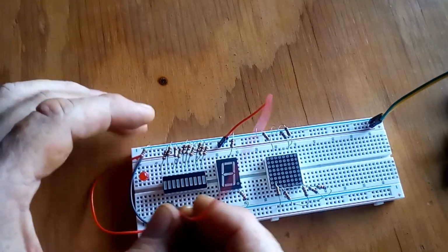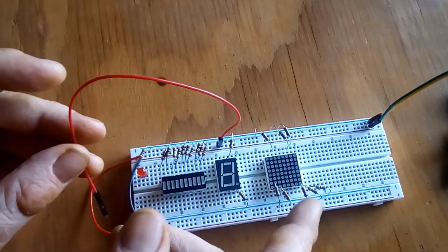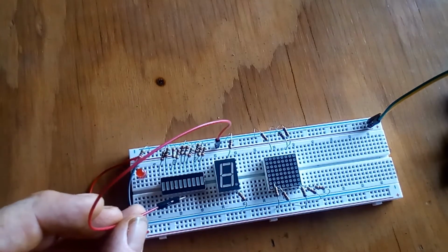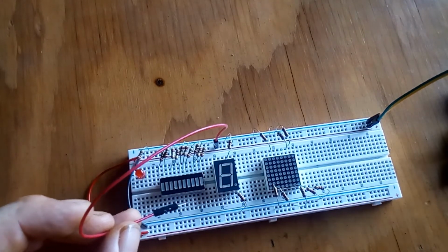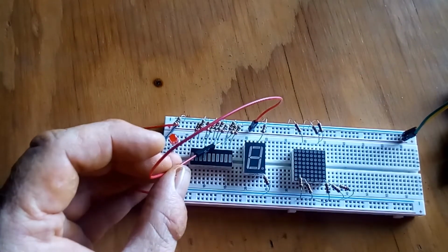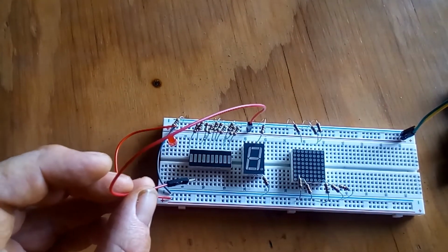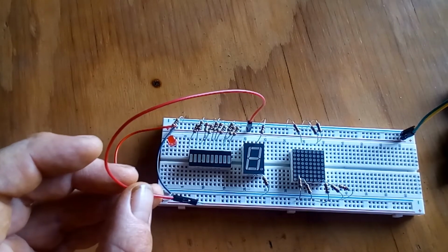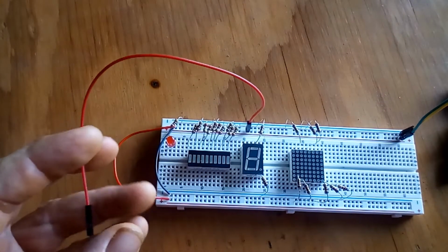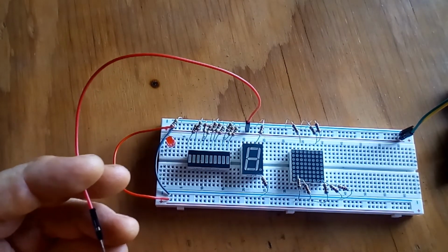And for all of these, really, there's 10 outputs. We wouldn't want to use 10 pins on a microcontroller to control that, so we'd probably use shift registers. Remember, a shift register controls 8 outputs with one input. So a serial communication input goes to 8 outputs.